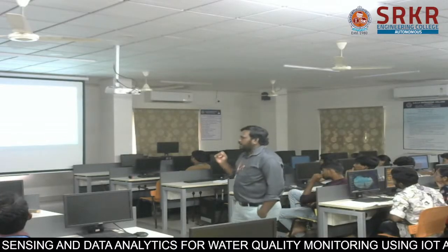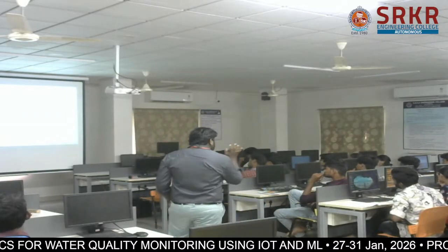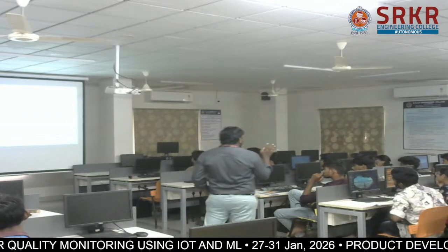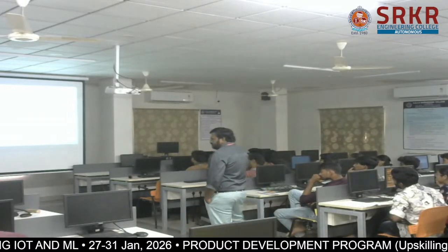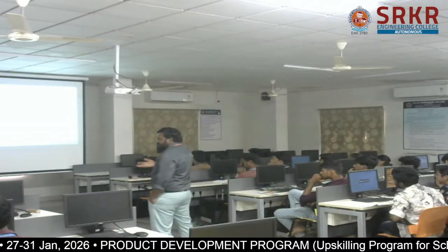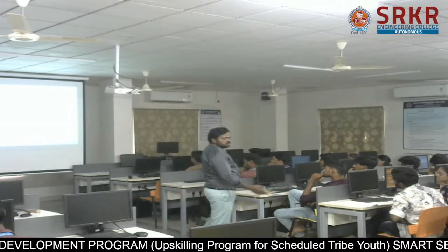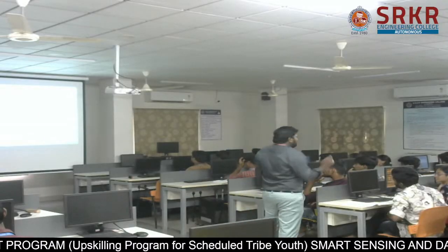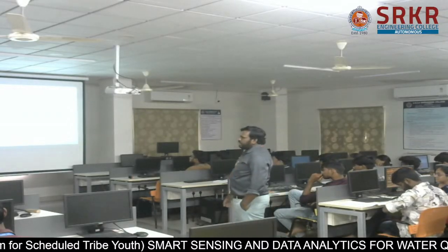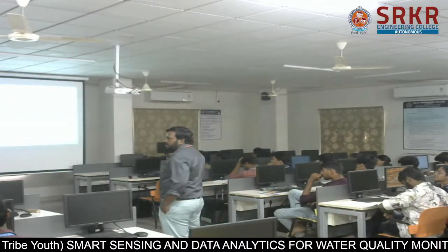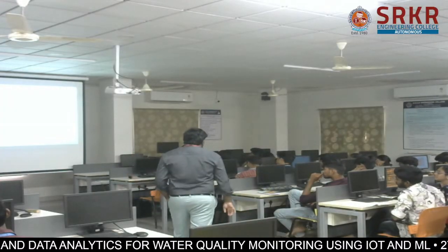We measured the pH value. Generally, the pH value should be 7 in the neutral case, right? If it is acid, the pH value is less than 7. If it is a base, greater than 7. That's what we know. But the acceptable range is 6.5 to 8.5. So that is the acceptable limit. If the water quality is good, acceptable, then the limit should be 6.5 to 8.5.